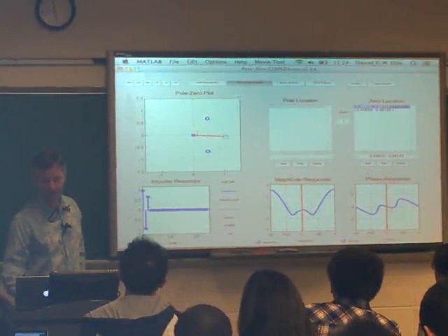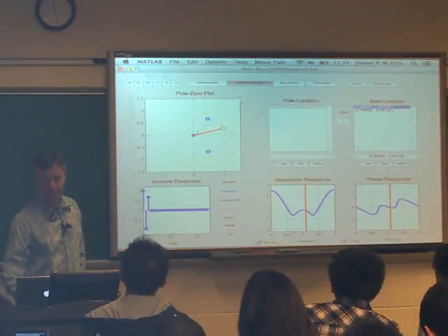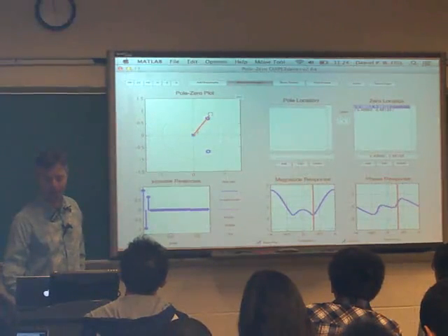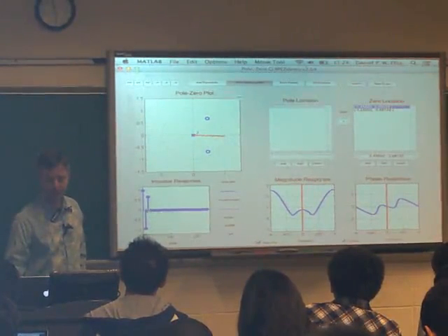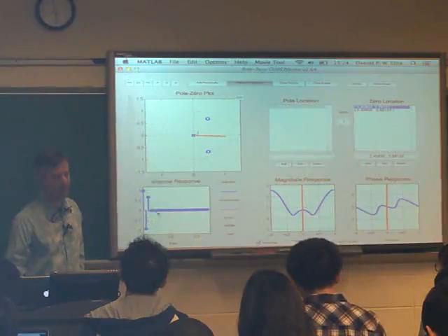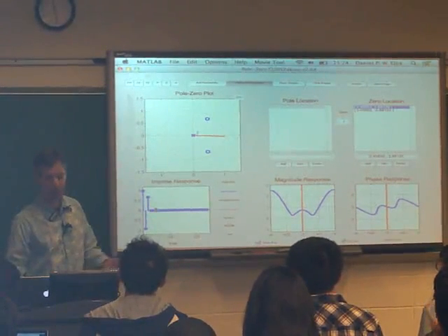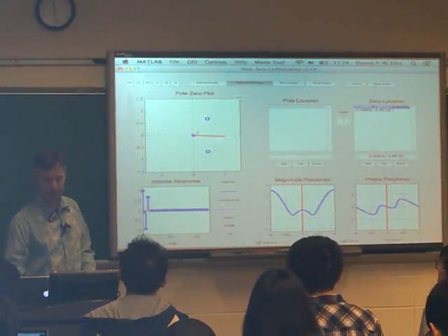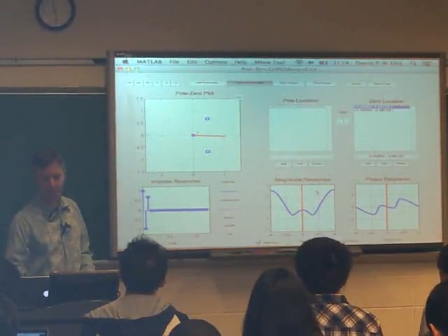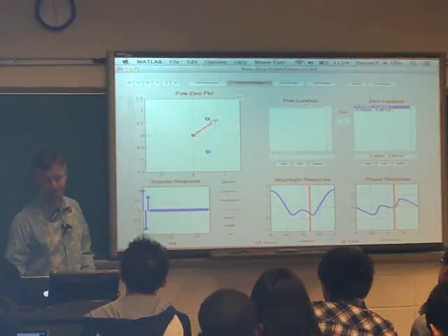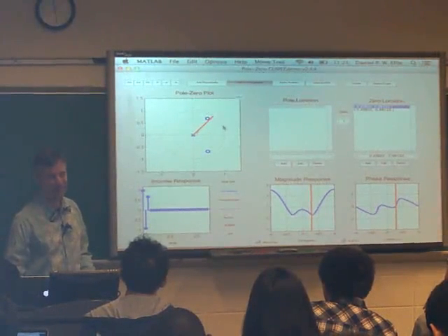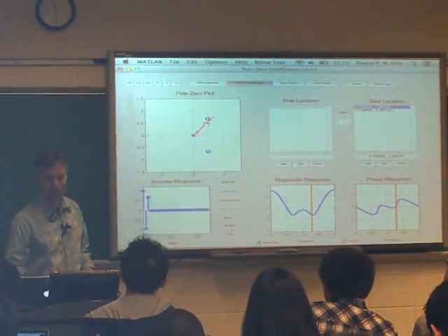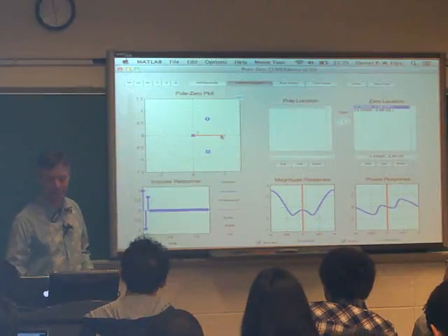And the phase response, it tends to be negative. It's going to have an overall negative trend because this looks a little bit like a delay. So if it were just a 1 here, then it would be a linear phase. But in the region of these zeros, the phase increases. It all makes sense in geometric terms if you think about them.